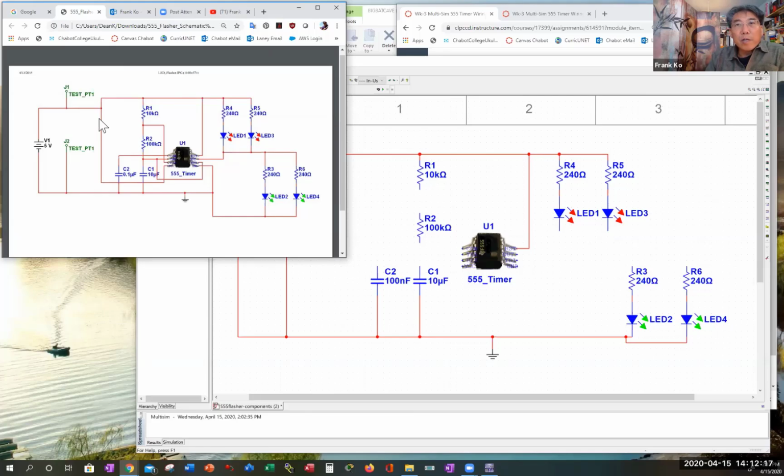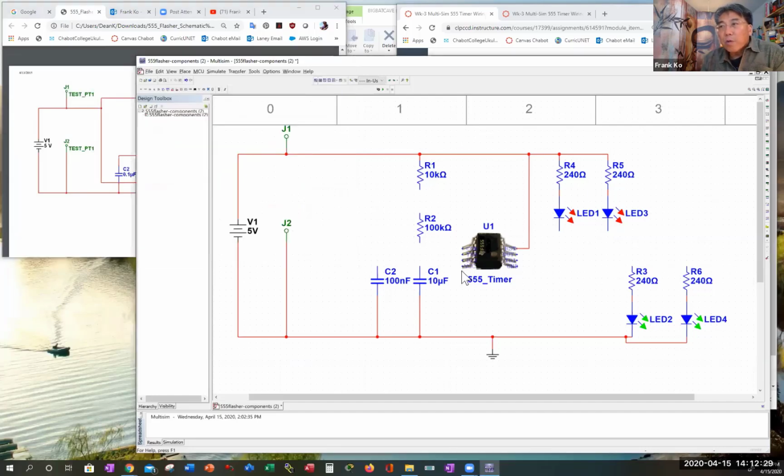There's one more wire that connects up here, and that happens to come from the 4th pin on the left. It comes down and comes up to here. So let's go ahead and do that. The way you do that is you make your mouse pointer come to this pin. It becomes a black dot. Come over, let go, click and come down, let go, click and come over to here, let go, click again, come up to here, and click in place. Now that wire is moving as we want it to.